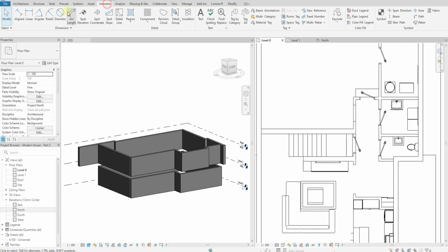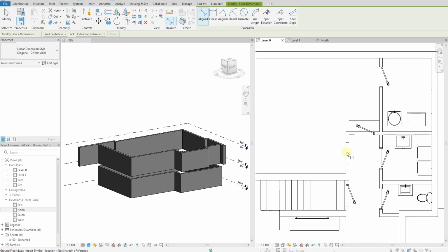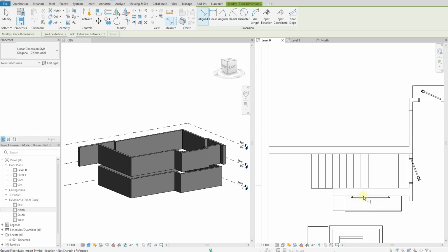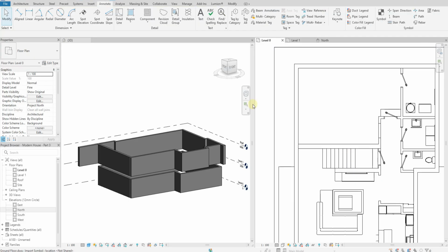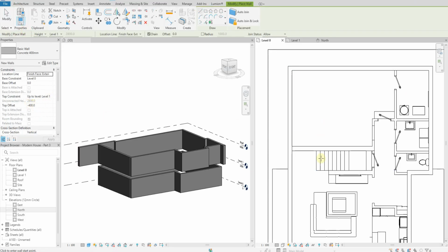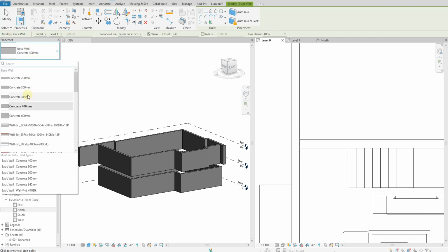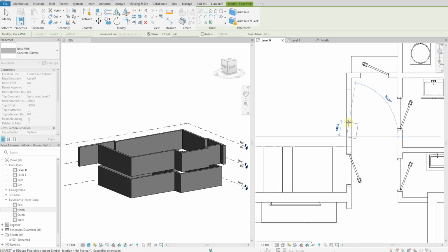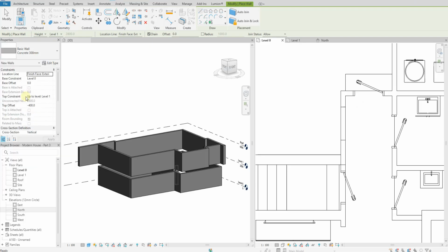Yeah. And also let's model some internal walls on the ground floor. They're mostly 300, and 150 there, and just 300 around the stairs. Okay. But for the ground floor we need to keep the offset of 400. Let's switch to the 300 wall. And later on we can change the type of walls if we want, with a different finish, etc.